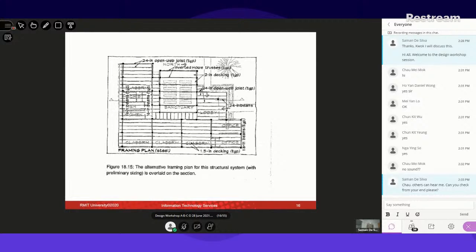And then we go and cover things up with the columns or the beams and whatever. Here, I don't think columns are required, because all the shear walls are there for all the gravity loads to be supported. So additional columns are not needed, but we require beams and slabs, of course.